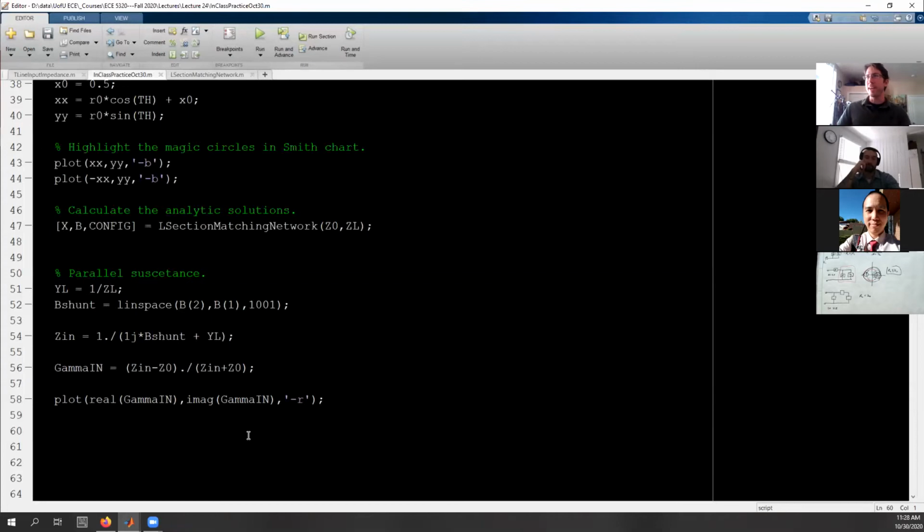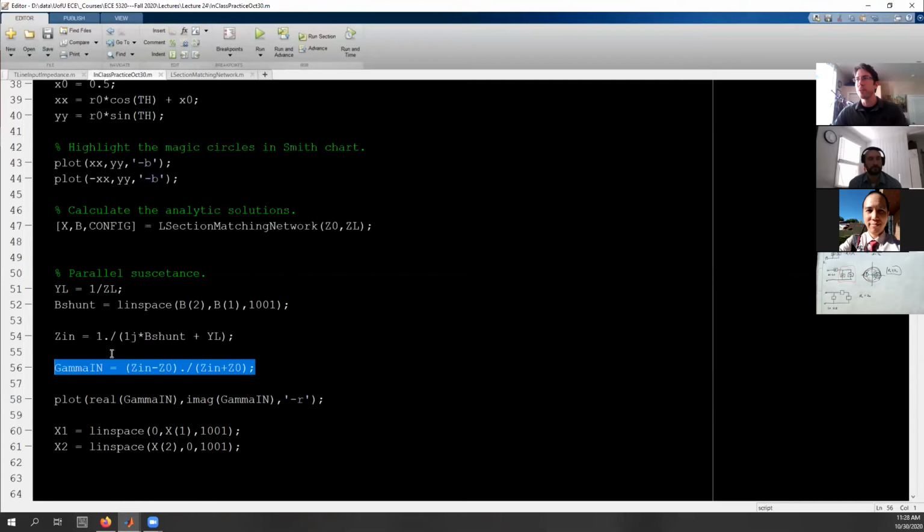And then now I have an X, so I'm going to call this just X series, I guess. This will be X of 2. Oh, except you got to be a little careful. So we're going to have to do two arcs now. So I'm going to go 0 to X of 1, like that. So I'll just call that X1. And then there'll be an X2, like that. And this one's negative, so actually I have to go from X2 to 0, like that. And again, we're going to calculate a new input impedance.